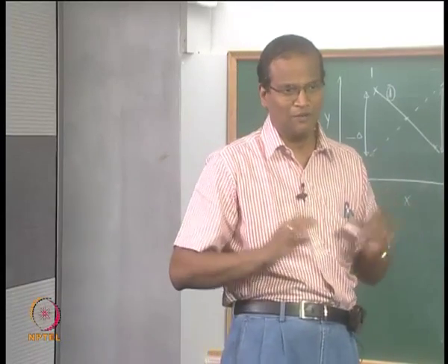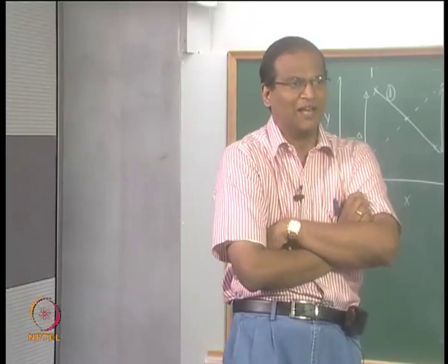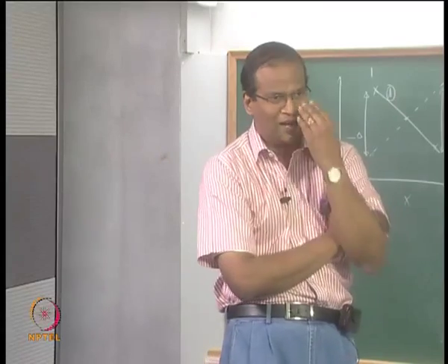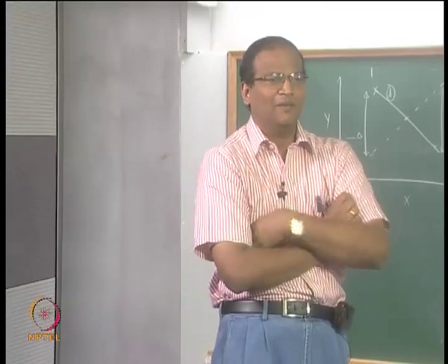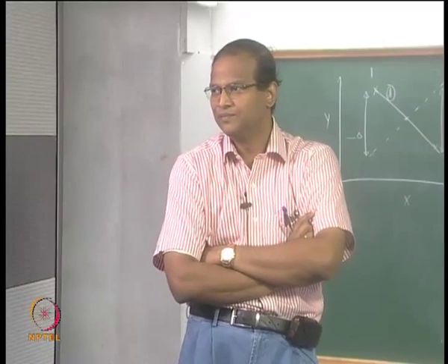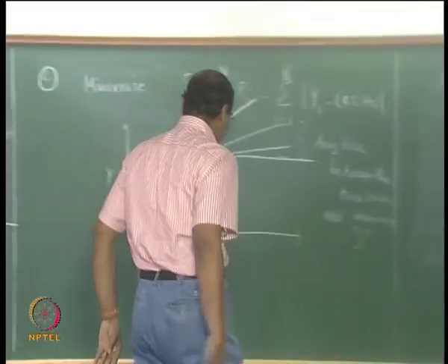There is something wrong with that point, either you did not allow for steady state to take place, or there is a fluctuation in the voltage at that point in time, or you made an error in reading the meniscus of the manometer. There should be some problem like that. So with all these strategies having failed,